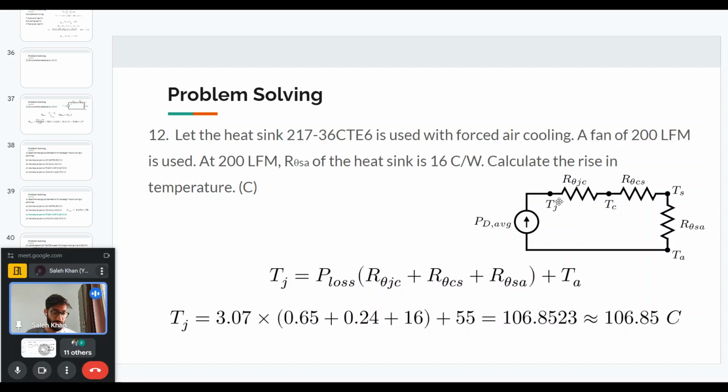But the idea of the thermal paste is basically that we want a very good physical connection between the device and the heatsink. Even if they are very smooth, there are microscopic elevations and depressions in the metallic surfaces. That is why we use a paste which goes inside these imperfections and gives a better connection, so that the heat gets transferred in a better way.